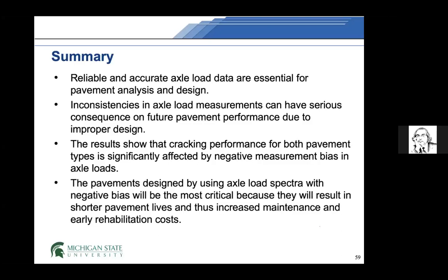You cannot apply the AASHTO design method for those magnitudes of ESALs. In the US, typically interstate will have about 10 to 20 million, and that is still a large extrapolation of AASHTO. So that's why we are moving towards mechanistic empirical design, because AASHTO has its own limitations because it's an empirical method.